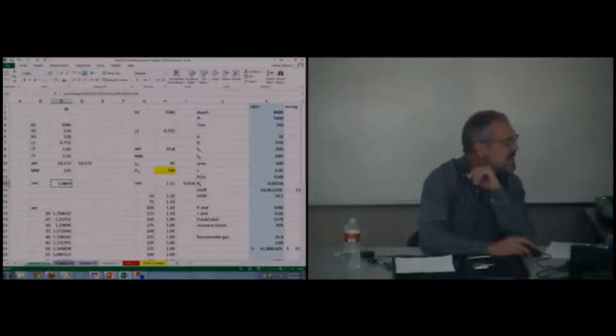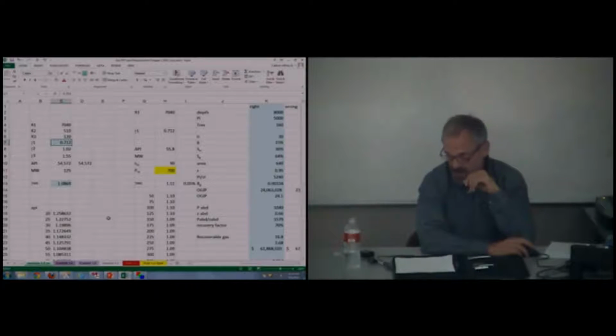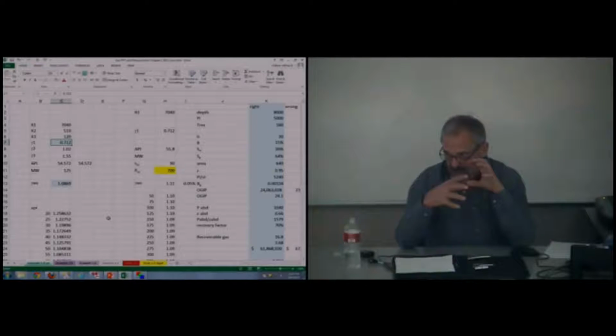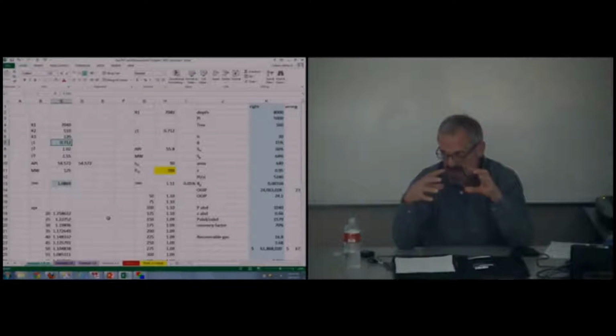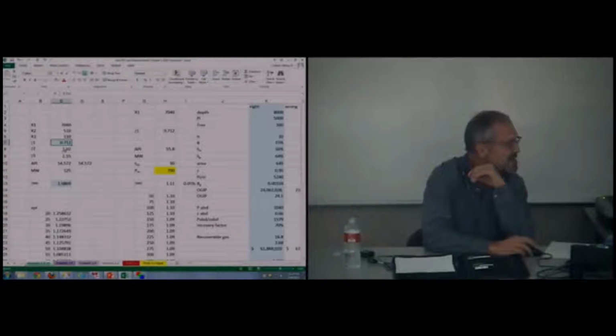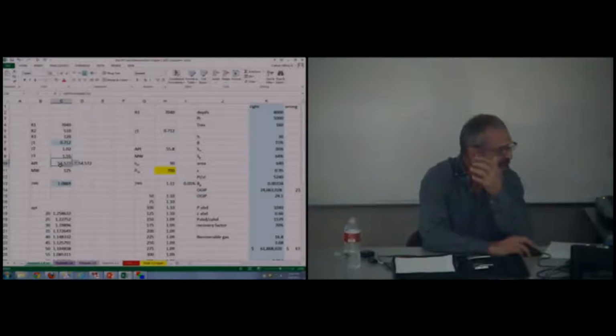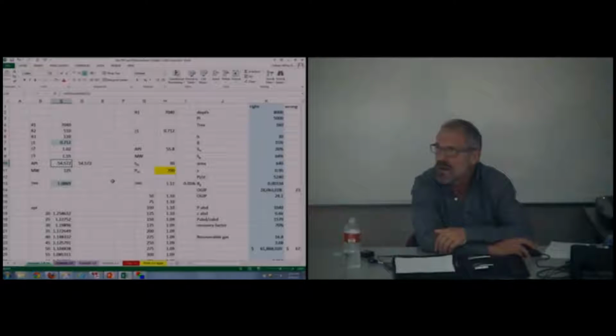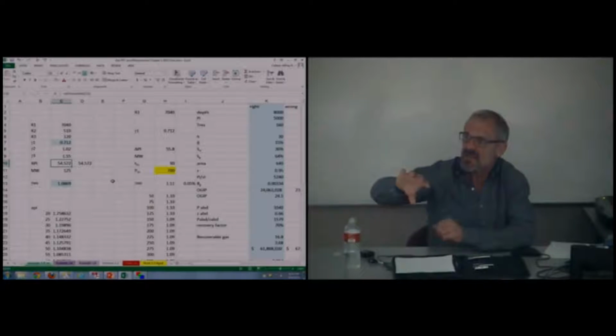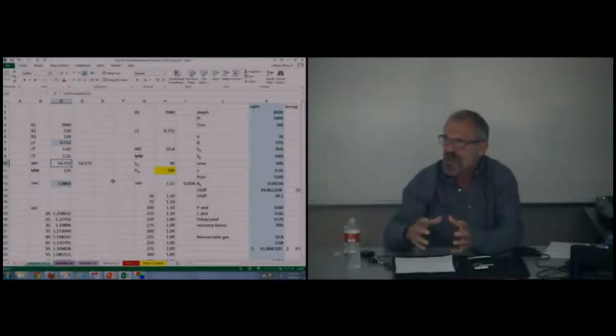This number right here is always going to be bigger than this number right here. Because just the way we separate gas out in the separators, these other two gas gravities are always going to be larger numbers because they're at subsequently lower pressures. And I've got to do something with this oil. When I add oil into the gas, I'm going to make it a richer gas.